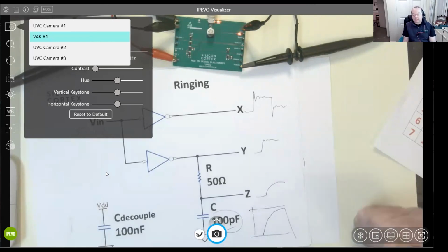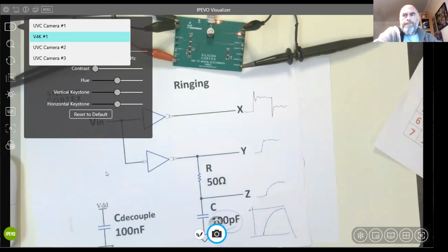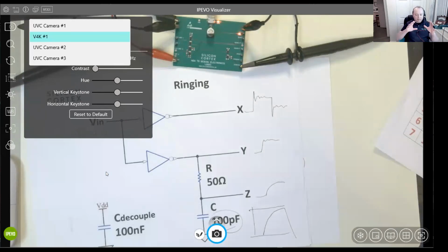When it comes to emissions and reliability, which is our penultimate one this side of the summer, we'll have a bit of a deep dive into how we can solve those problems. Opto couplings is an option. If things are going to be a long way away, and you've got your Raspberry Pi and some sensor, you could run RS485, which is pretty industry standard, rock solid. It's just a differential UART, which is dead easy to set up. That would probably be the way I would do it.